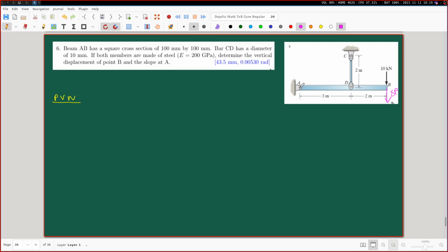First of all, you would have determined the reaction forces, the force here, and then if I had asked you to determine the shear force anywhere along the beam, you would have immediately been able to do it. Now, is the situation any different now that we have removed this 10 kilonewton force, and instead of that, I am applying this delta P? Situation is exactly the same as far as the statical mechanics is concerned.